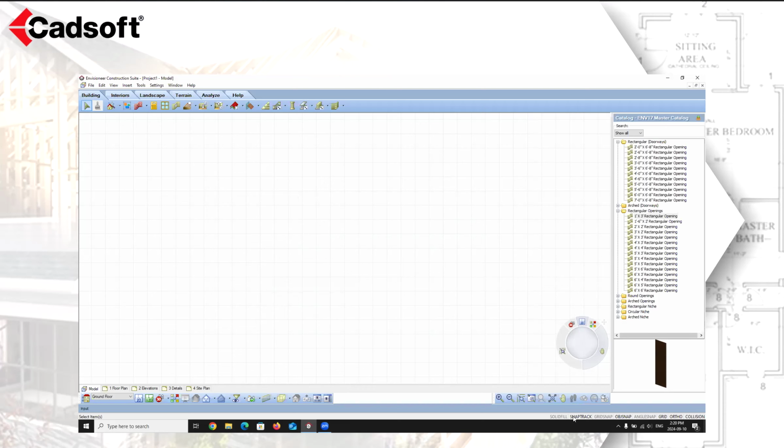The next is Snap Track. Now, this is a tool that I do like to have turned on. This helps you draw objects at specific angles, or positions relative to other objects. When snap tracking is turned on, a temporary alignment path will appear on your screen based on the object snaps of points that you're referencing. So again, I like to use this to help me recognize different areas of my drawing. If I want to line something up, I will keep snap track turned on.